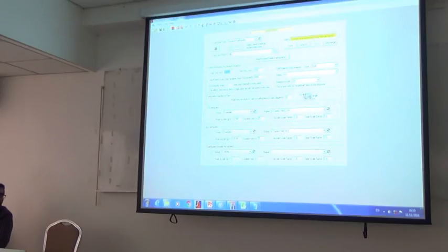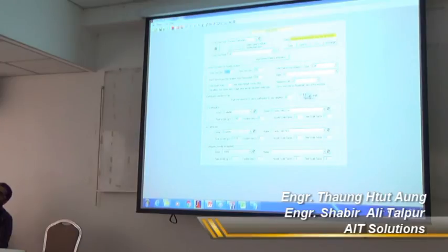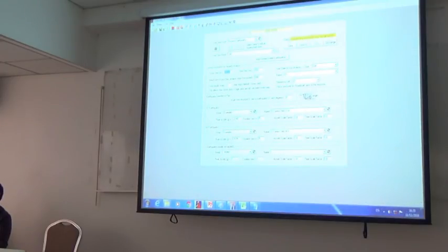For the slab modeling in Perform 3D, we just model the slab to consider the in-plane stiffness of the slab. In Perform 3D, we can transfer the weight of the slab to the vertical member, but only from the four nodes. So, for example, if the slab is supported by four beams at the perimeter and we want to transfer the self-weight of the slab to the beams, the program cannot transfer it, because of the four nodes, it will transfer directly to the column, not to the beam. So what we normally do is we model the slab but change the weight